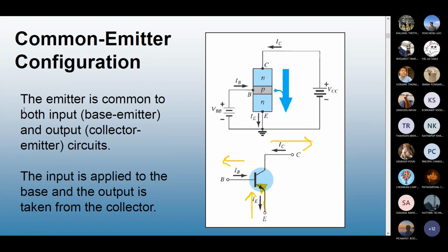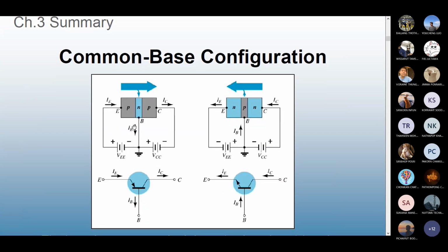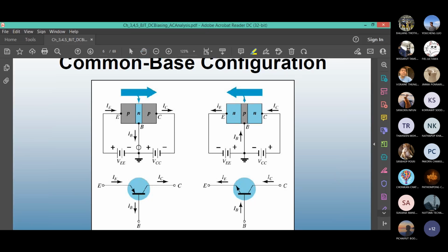So after common emitter, what else can we do? We can do other configurations because we have two other terminals. Common base: now you put the base to the ground. Here is the base on the ground. It is common to the input side. Now the input is the emitter side. Also, the ground is common with the output side. Collector is the output side. So this is a common base PNP configuration. Notice how IE equals IC plus IB. You reverse every direction and polarity with the NPN.